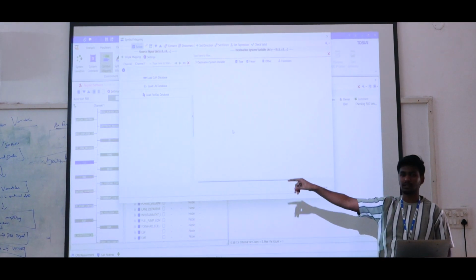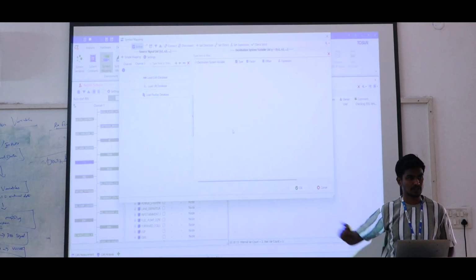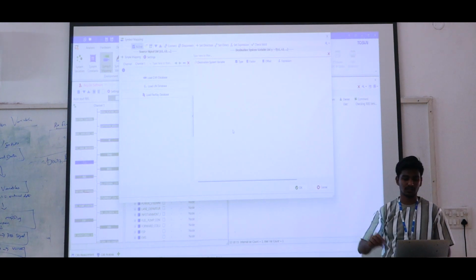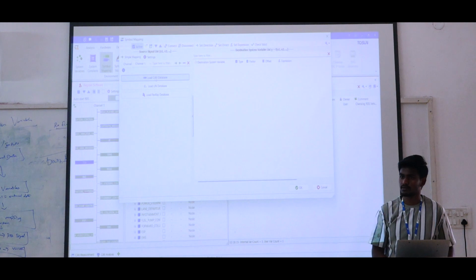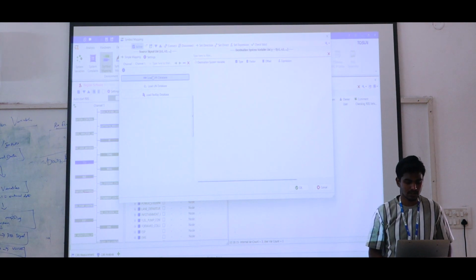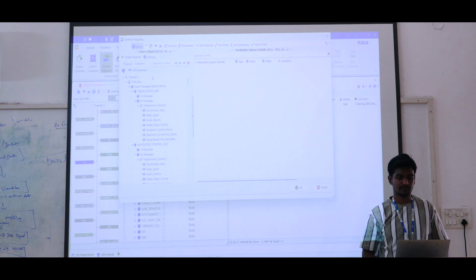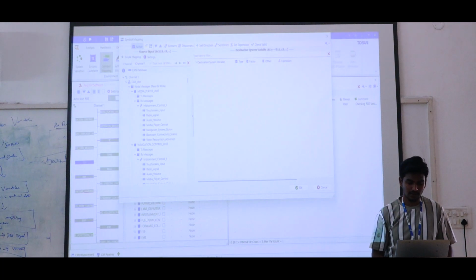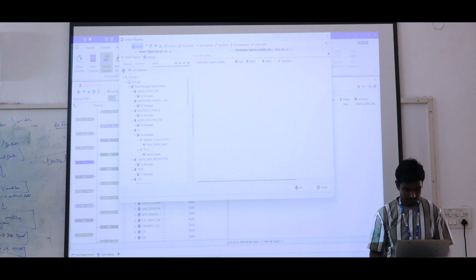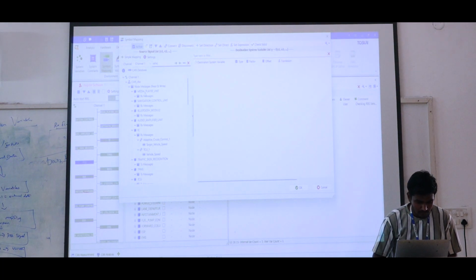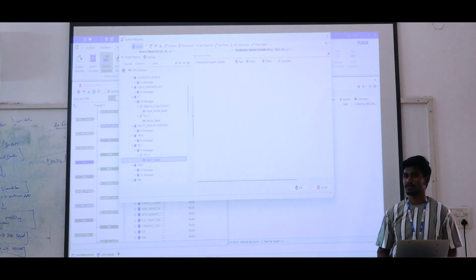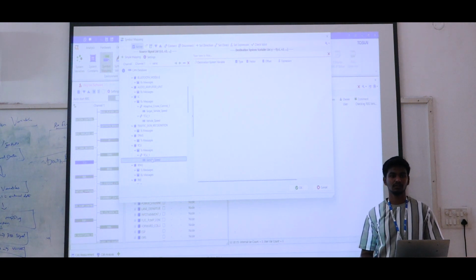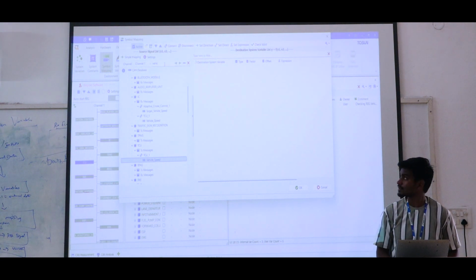So next we will move to variable to signal. First direction, variable to signals. Here we have the CAN load database option. You just click this, it will open our database. So here you can search vehicle speed. Vehicle speed you can take from the TCU node. The vehicle speed signal is there. Got it? You can search in this search box.